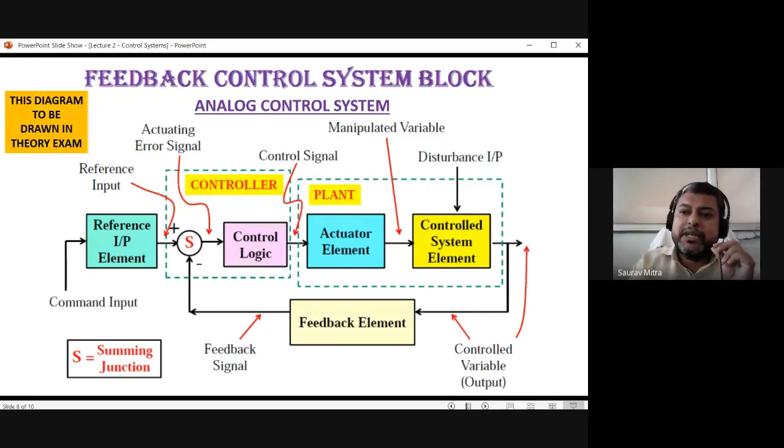So these are the two downsides. If you want, you can write them down. First, the disturbance is reflected at the output side, and the control parameter gets damaged. The controlled output is no longer a controlled output; it deviates from the actual value. That is the first thing. Second, it takes some time.